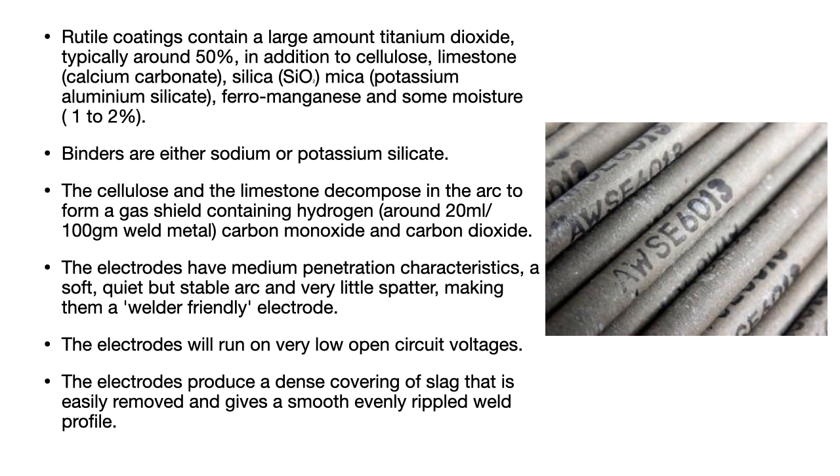Technically, just for your information, welding is designed in such a way that, you see, in welding an arc is produced to generate heat. So basically it is I squared R or VI in terms of physics. The basic principle of welding is that it is a low voltage, high current phenomenon. It is designed in such a manner that the voltage requirements are low.